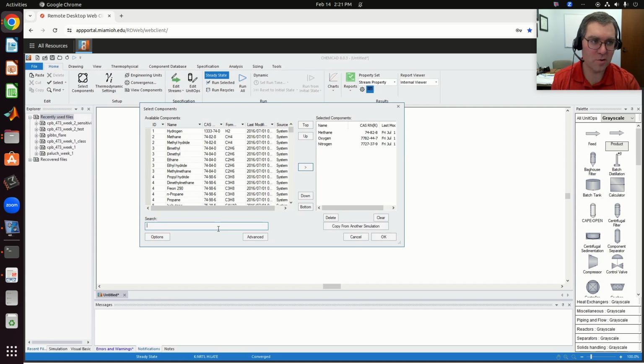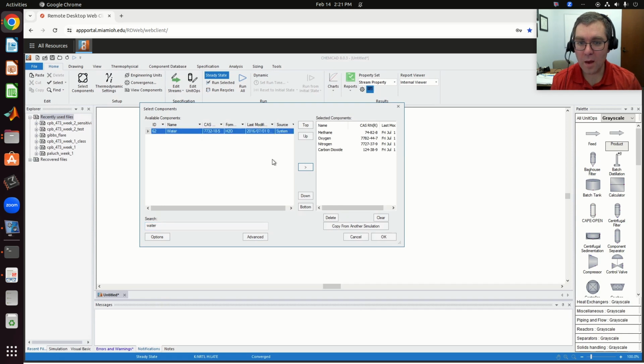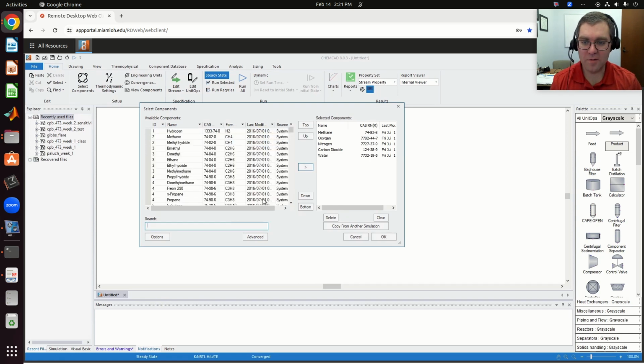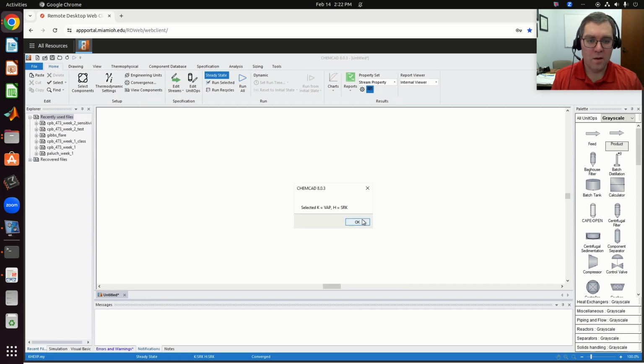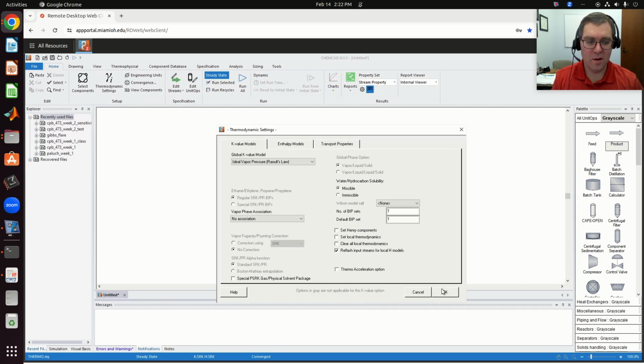But I know for a basic combustion reaction, I'm going to expect some carbon dioxide, CO2. I'm going to expect some water. And just because I have CO2, let me also specify CO, carbon monoxide, and let's see what we get out of our simulation as well. So I expect my standard combustion reaction to give CO2 and water, but let's throw CO in there as well and see what happens. Okay, so I'm going to click OK. I'll accept the recommended thermal model, and that is all good.